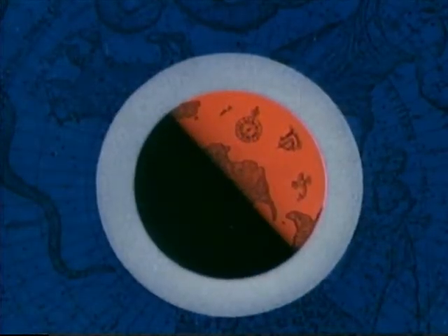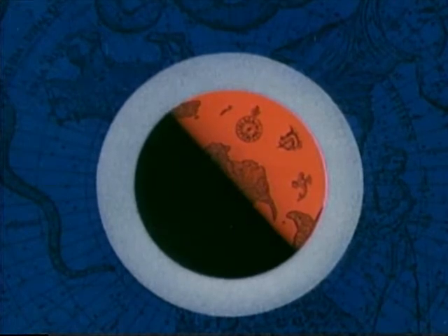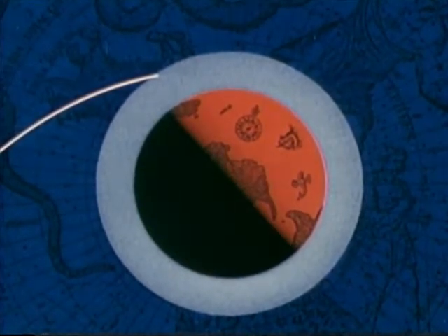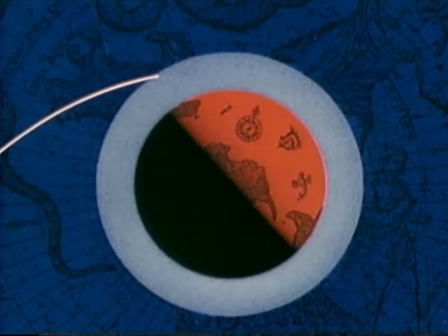To understand how the entry trajectory is shaped, it is necessary to understand the conditions existing at entry. The spacecraft will enter the upper limit of the atmosphere at an altitude of 400,000 feet. This altitude is, by definition, where the perceptible atmosphere of Earth is first encountered. It will enter at a speed of approximately 24,500 miles per hour. This is a speed considerably greater than that required to put the spacecraft into circular orbit around the Earth.